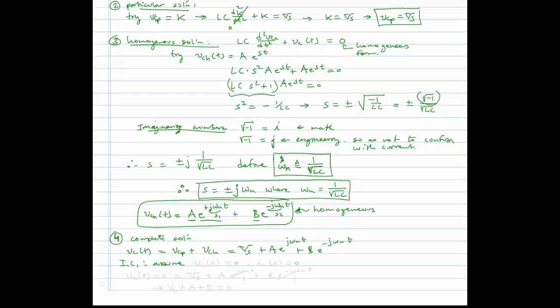Now that we have both an inductor and a capacitor, we need to specify two initial conditions. This is just like a mass hanging on a spring that you're going to excite. You would have two initial conditions: the position of the spring, is it at rest, compressed, or stretched, and then the initial velocity on the mass. So we have the same thing here.